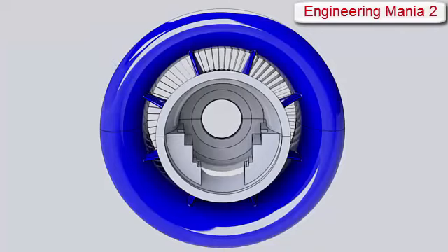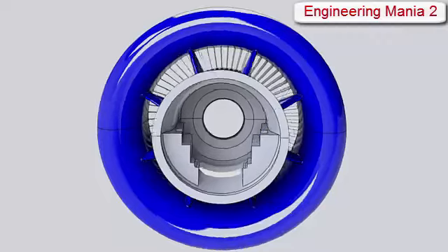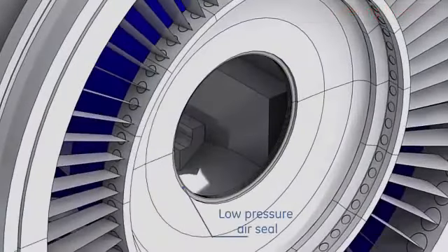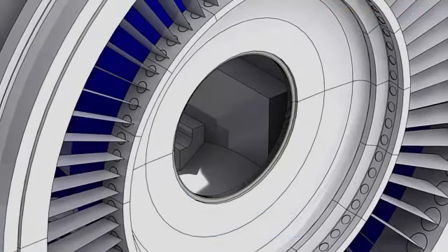The bell mouth function is to direct the air normally and uniformly to the inlet guide vanes for efficient airflow control and better inlet flow coefficient. The lower half of the bell mouth provides support for bearing number 1. A stationary labyrinth seal is installed at the aft end of the inlet casing to prevent suction of contaminants into the compressor.